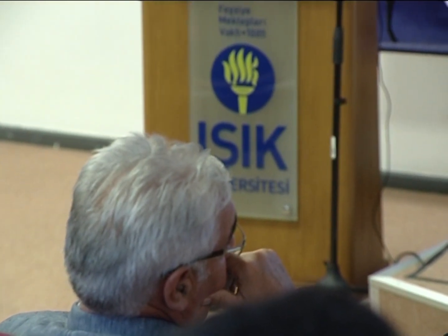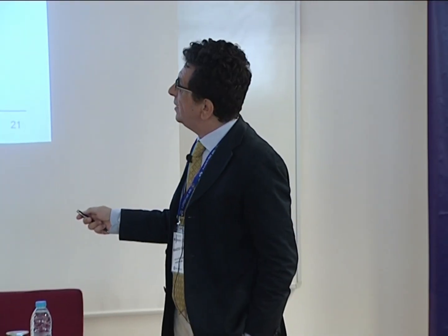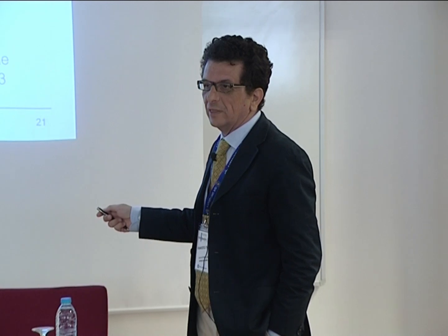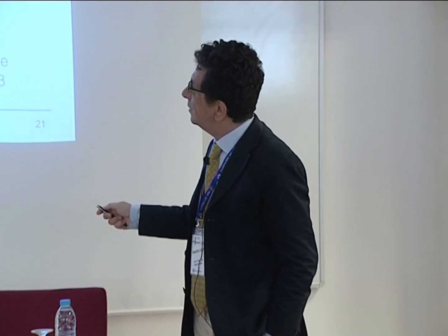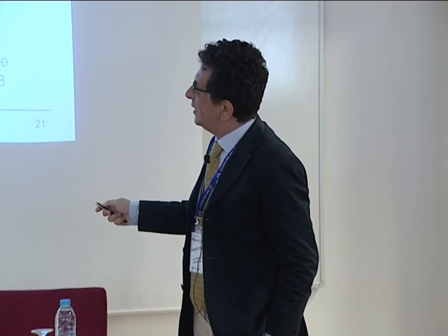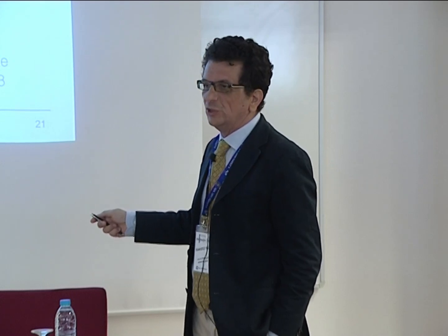But think about it in a different way, because when we involve IP3, we're thinking about something which is not anymore under small signal operation. We are in large signal operation. So let's assume this difference is large. What's happening is that this node is not anymore a virtual ground. It is, on the other hand, following the gate of the device which is driving.